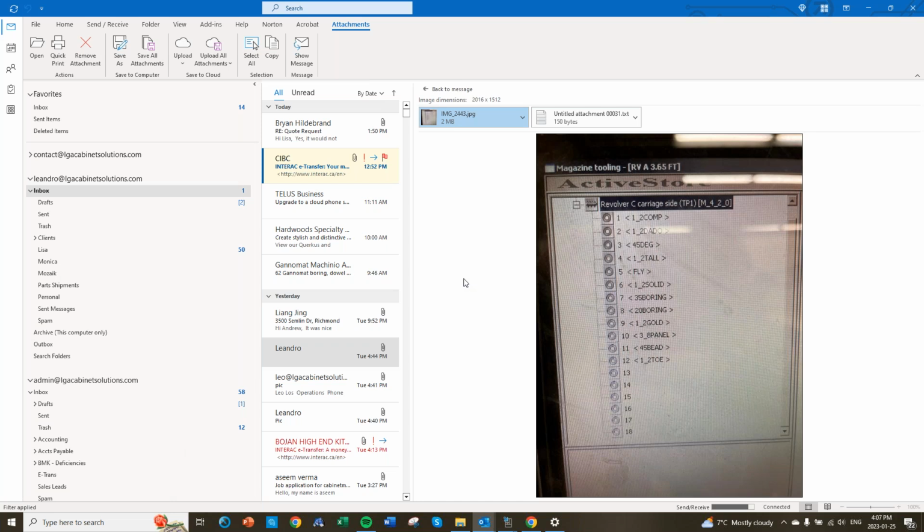New. I'm probably gonna add some more there. Sure, no problem. Because what happened is, I'm taking over the CDC and they use the cabinet vision. Okay, and so they use the 1/2 inch to cut and not the 3/8. Okay, so what we could do is we can make some tools. We'll call it 3_8 comp. That'll be a 3/8 compression. We're going to follow the same.